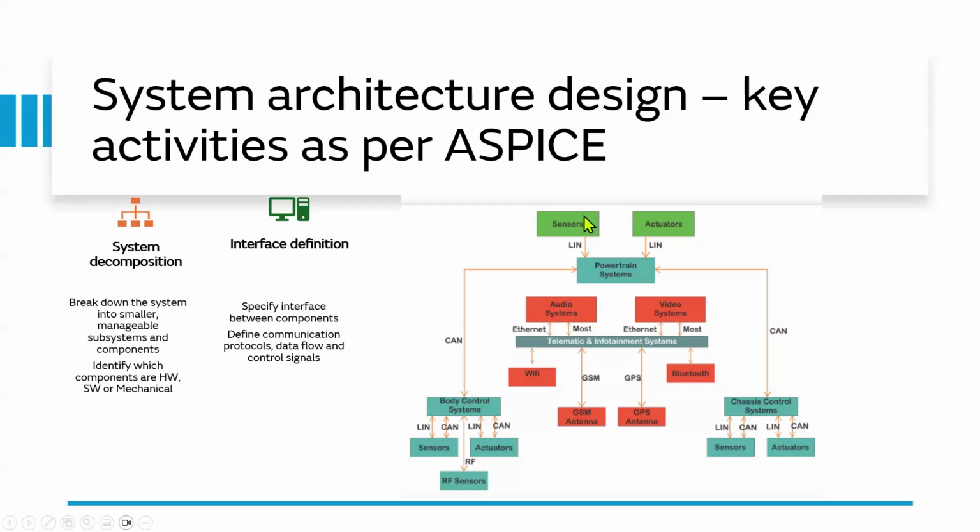So which means you may have, from different sensors, it could be a voltage sensor or a current sensor, then we may use the CAN network. For example, from chassis systems. And then you may have LIN for some other messages as well. And then we have other types of comms like Ethernet. This is fairly faster, and most of the OEMs now are moving towards Ethernet. So you define these interfaces and how you exchange the data.